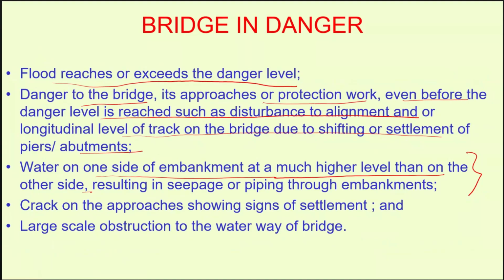Check on the approach showing signs of settlement, and the larger scale of obstruction to the waterway of the bridge. So all these things need to be seen. Some repetition is there, but this is important.